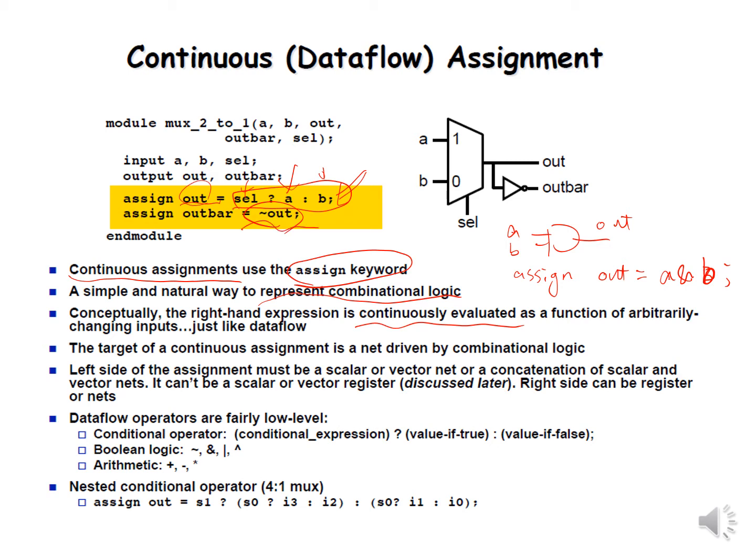Any input change will cause the statement to be evaluated, just like a data flow. By having an assign statement, we are generating a wire net driven by combinational logic.